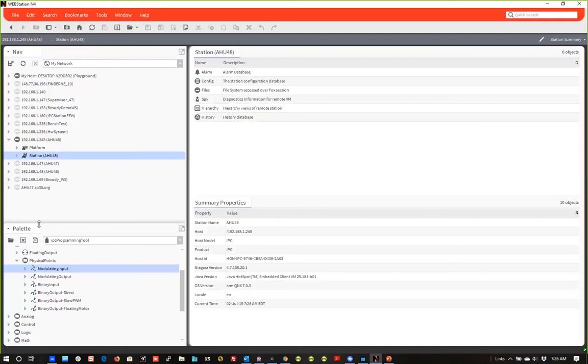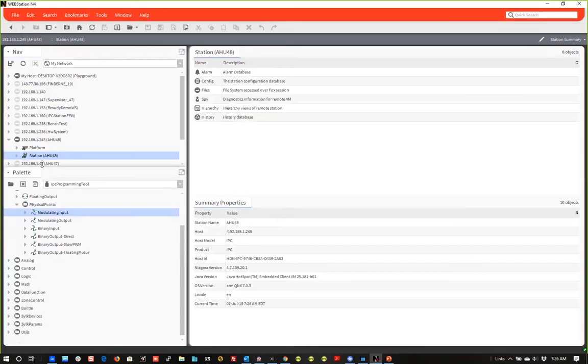I think, Frank, if I recall, that is now in steps of 300 microvolts or something like that. You're correct. So what that basically means is, if before between 0 to 10 volts we had a 100 step resolution, now we might have like 300 to 400 step resolution. So a lot beefier inputs and outputs, and the benefit is we just get much, much better control.